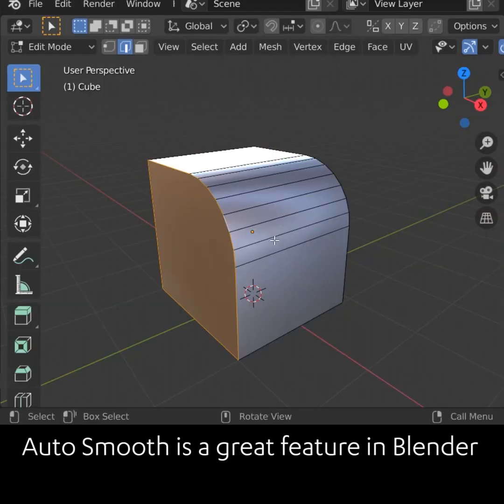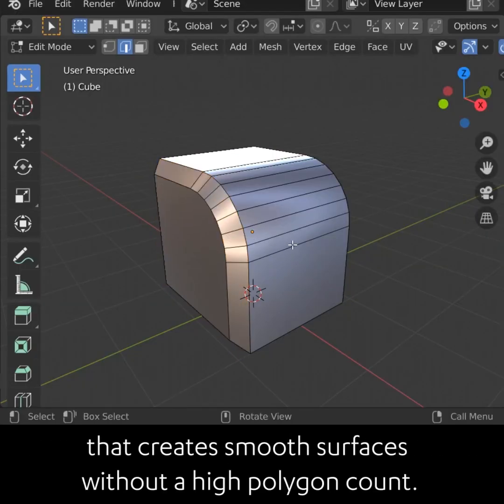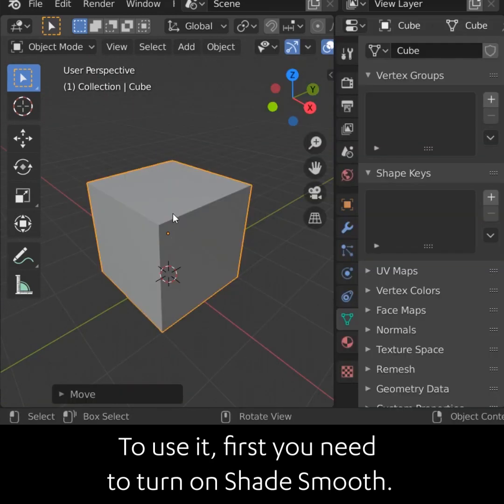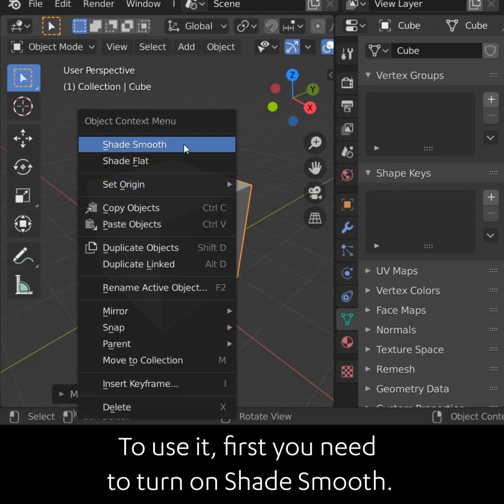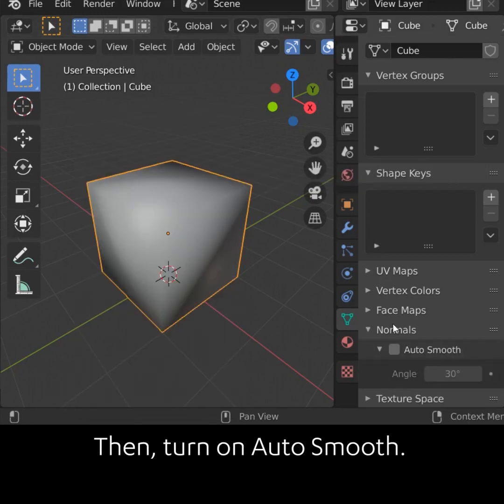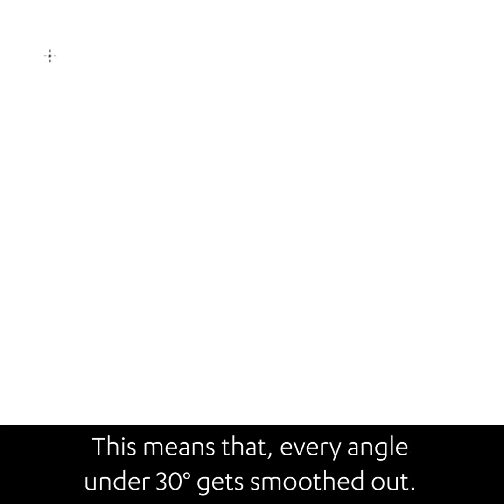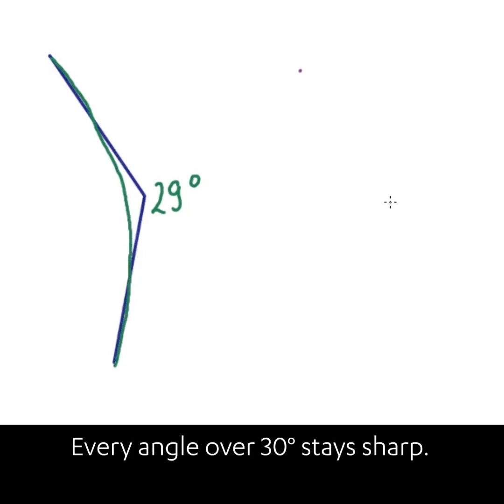Auto Smooth is a great feature in Blender that creates smooth surfaces without a high polygon count. To use it, first you need to turn on Shade Smooth, then turn on Auto Smooth. An angle of 30 degrees works well in most cases. This means that every angle under 30 degrees gets smoothed out. Every angle over 30 degrees stays sharp.